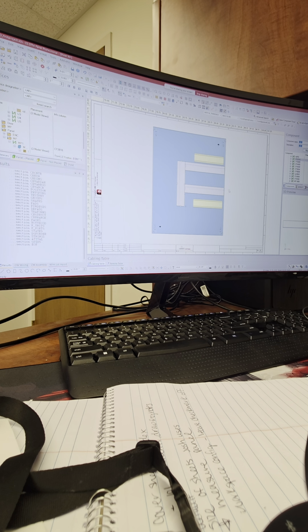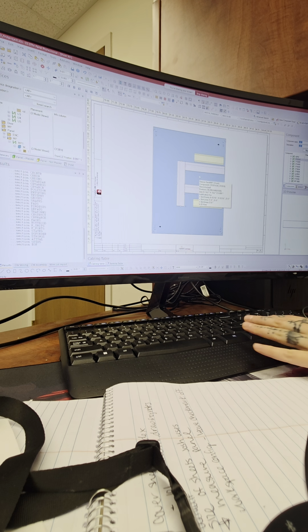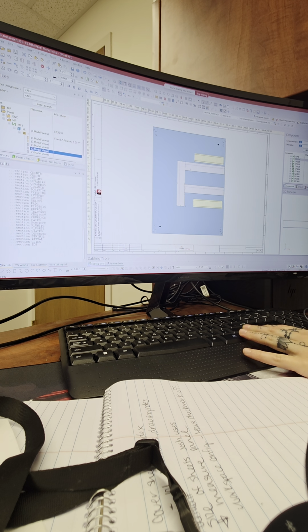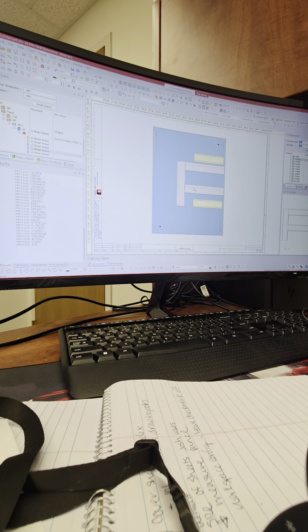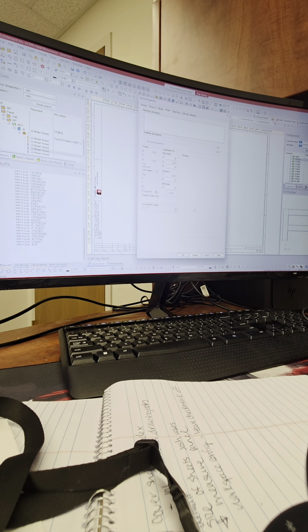Yeah. So what you can do is right click on these devices, on any of these ducts, or multi-select them. You can do all at once. As an example, right click on these objects and we'll say device properties. So let's click on the devices tab. That's where the majority of this stuff happens from a BOM perspective.